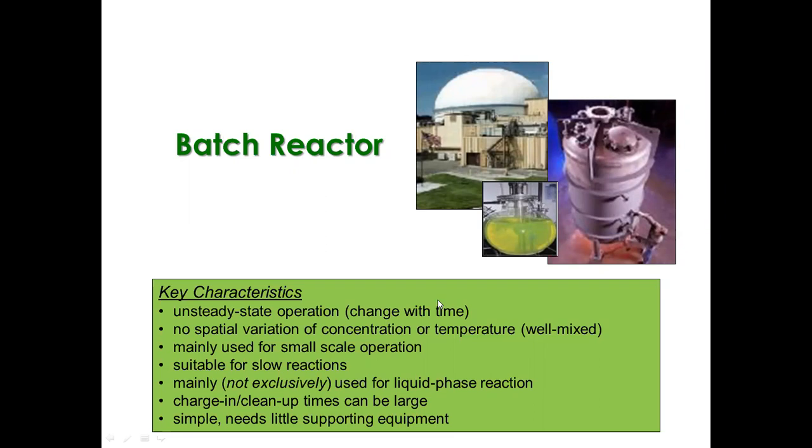The thing with it is since it's for slow reactions, it's for small scale operation, it's simple and needs very little supporting equipment. Okay? Not like the other two, the steady state reactors, because they may need supporting equipment, especially when we speak of reactions that need the addition of heat or the removal of heat in the mixture in the course of the reaction. So that's for the batch reactor.